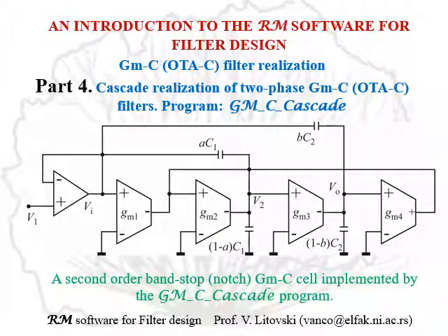That is exemplified here for the case of the notch filter. As we can see, to the input terminal denoted by VI, we have two capacitors connected, which would reduce the input impedance of the cell, and which will load the previous cell, which has a high impedance, and so the necessity of the unity gain amplifier is obvious.